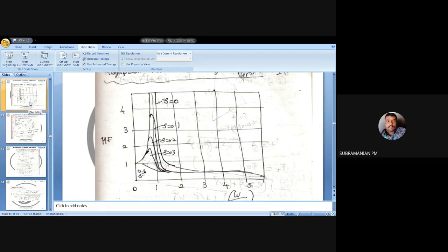So that is the next influence. You can see, irrespective of the damping, whatever the damping ratio is, I will have a maximum amplitude before omega by omega n is equal to 1. Omega is the frequency of forced vibration and omega n is the frequency of natural vibration, otherwise I can use the word undamped vibration.